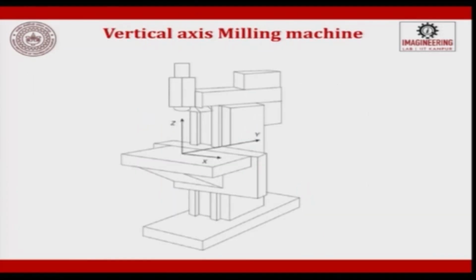So, for a vertical milling machine, you will see this is your spindle axis. I have said plus and this is minus, assuming towards the workpiece, away from the workpiece. Now, if you try to fix this as an origin, when you move this side it is minus and this side it is plus, and it is plus here and minus this side for the y axis. So, by this way you will be able to fix the axes for a vertical CNC machine.